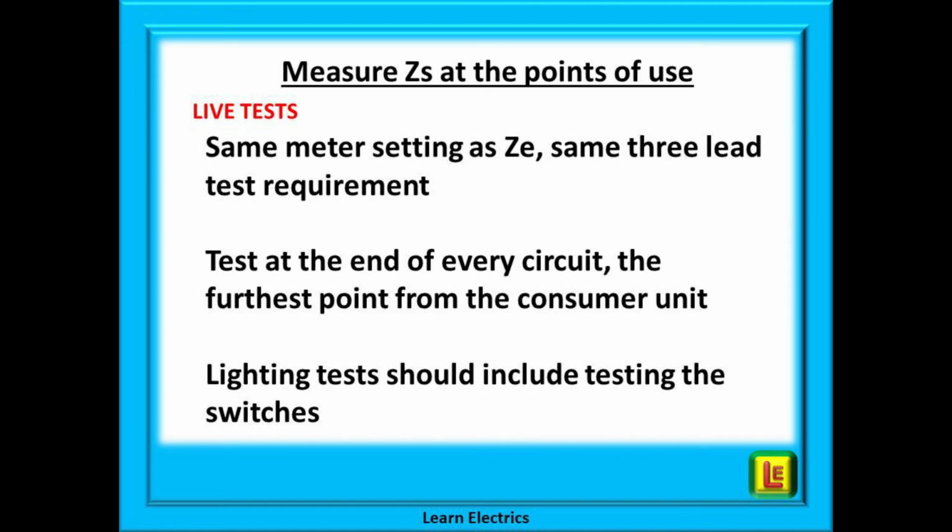Now we'll move on to ZS, or the whole system. The impedance of the whole length of a circuit from the point of use to the substation and back again. These are still live tests, and at Learn Electrics we always encourage safe working practices. If you are not sure at any time, stop and ask.